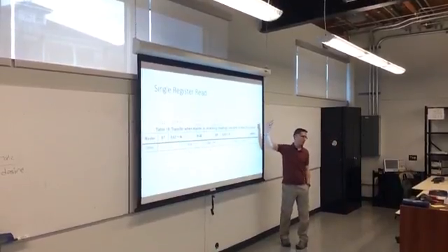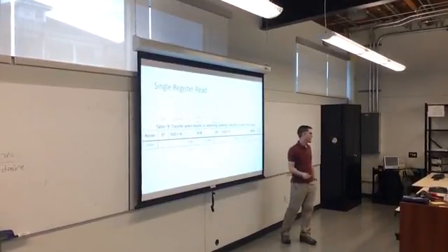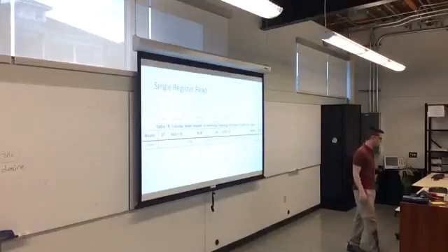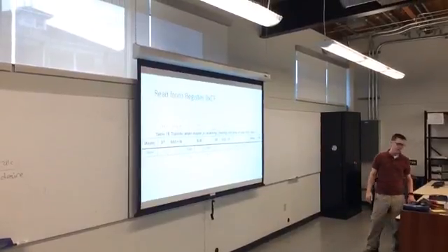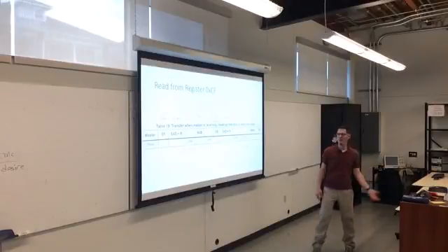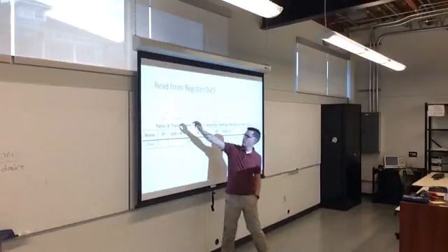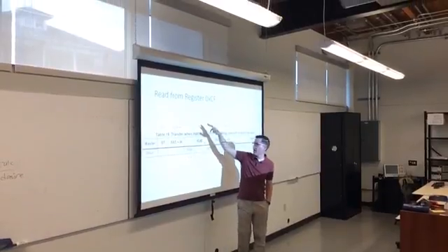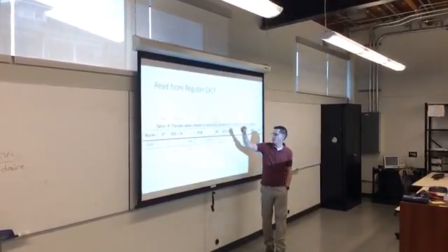So the way that this works is if you wanted to read from register CF, you would do a write transaction, you would write CF into the device, you would do a repeated start, you would do a read transaction, you would get the data back from that. So the big difference here is that you're going to write the address that you want to later read, and that you have a repeated start.